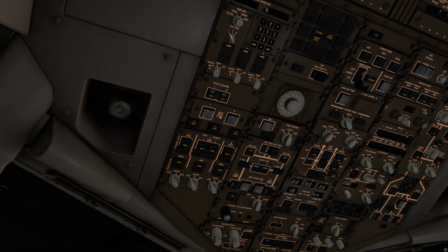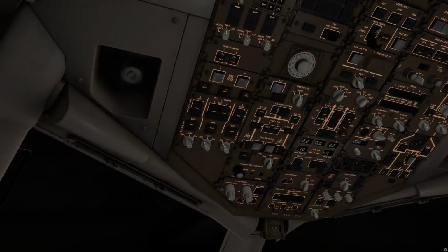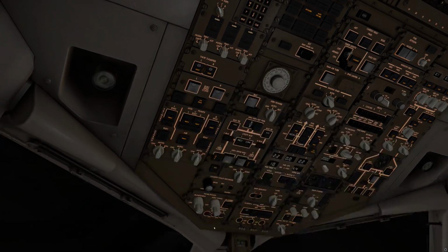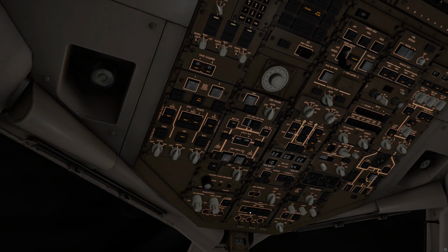We'll turn on our yaw dampers. Our EECs are on. Our hydraulics on. Do a quick scroll here. Engine generators are off. That's fine. We have our position light on. Our logo light is on. Here are the emergency lights. We'll go ahead and arm those, imagining that passengers would be boarding here.